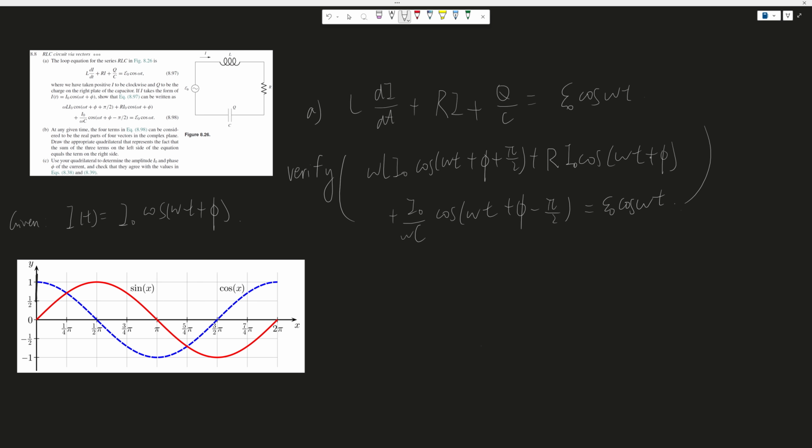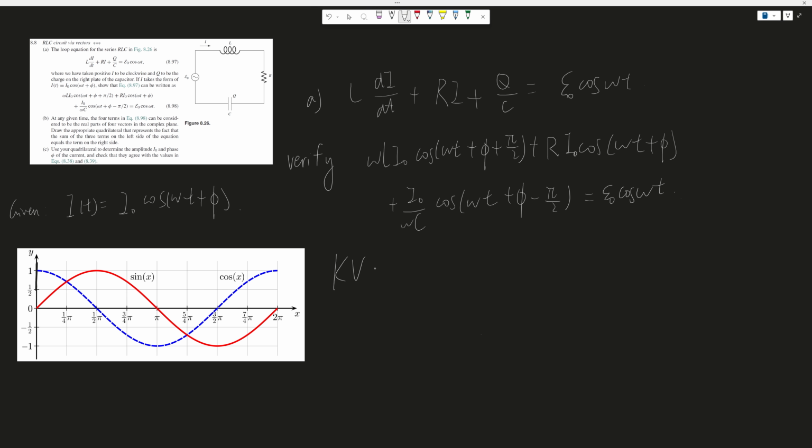What is this formula exactly? Well, it is Kirchhoff's voltage law. This law says that when we loop through a circuit, the potential difference is always zero. So the voltage source provides an EMF, and as the current goes through each individual component of the circuit, it causes voltage drops. When they all add up, we get zero. And so this is where that formula came from.